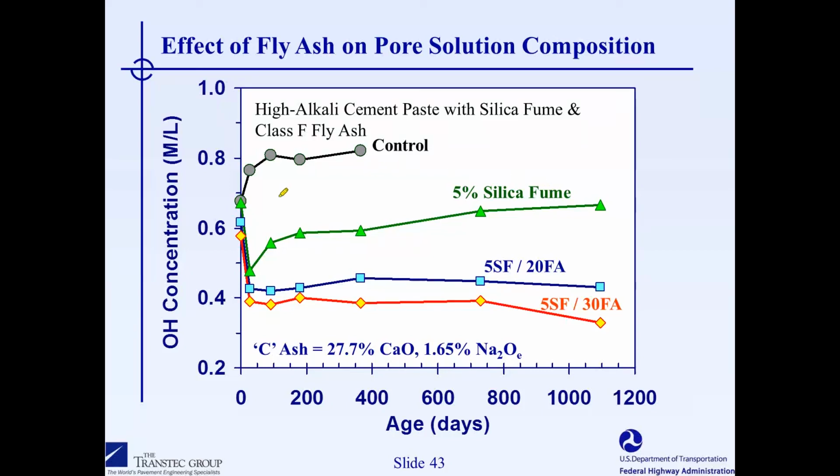This graph shows a similar situation for silica fume. Silica fume is also very effective in this role. It's effective much faster because silica fume has such a high surface area and there's such a large amount of reactive silica. We get a very rapid reduction in alkalinity. At low levels of silica fume, there is a bit of concern that some of this alkali is regenerated as the alkali silica fume complex is converted to calcium silicate hydrate.